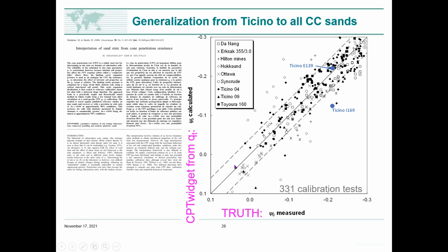And the diagonal line at the center is a one-to-one equivalence. And what we have here is 80% of the data lies within a state parameter of plus or minus 0.04. I think, and this is back to my engineering judgment, most of this scatter is actually lack of experimental precision with this chamber testing.